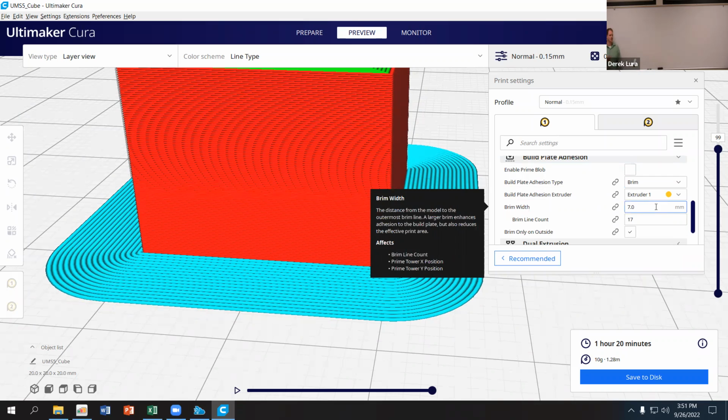As you print larger and larger parts, and mostly longer parts, the amount of contraction you get as the part cools becomes more significant. And so the force trying to peel those parts off the build plate becomes stronger. If you're putting a little part, usually it's not going to be an issue. Unless it's a really kind of thin, tall something, then you're going to be in trouble.